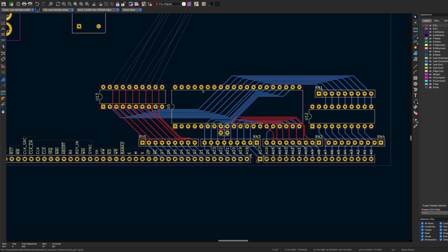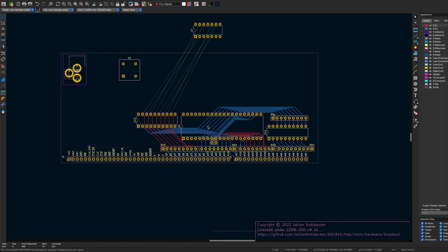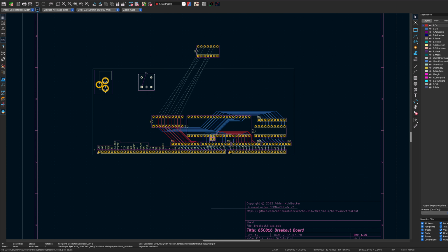Right, so I think this is much better now. The CPU is closer to the control lines. The data bus is driven with very short traces here. The multiplexed data and bank address bus is a bit shorter, and the bank address is a bit longer, but I think that's fine. So I think I will keep this. I'm going to start routing other areas.